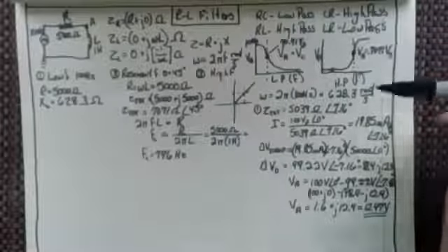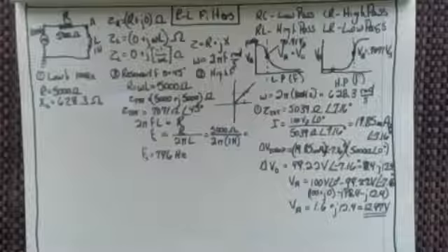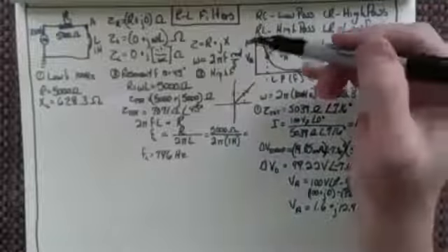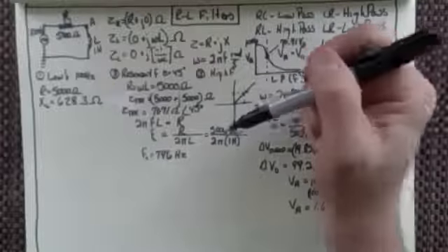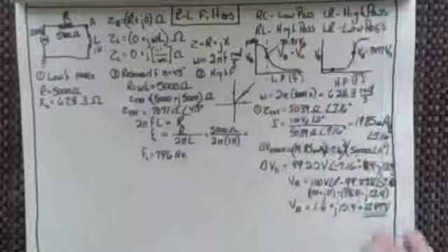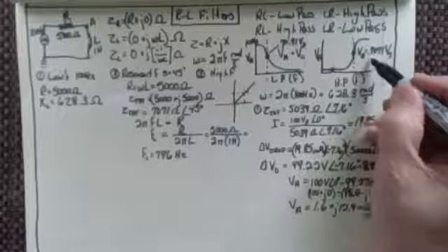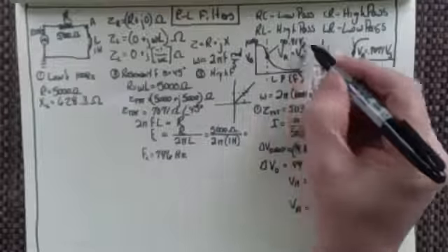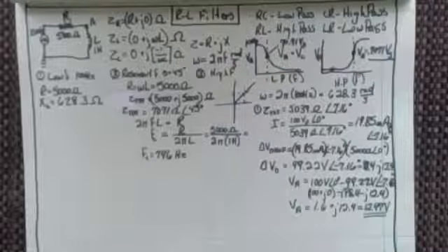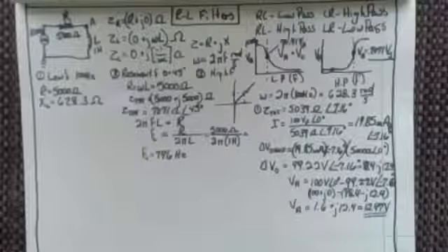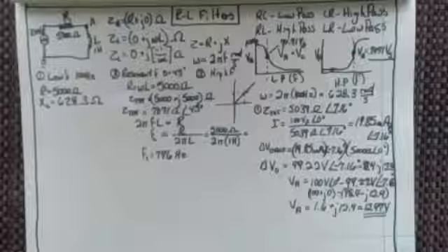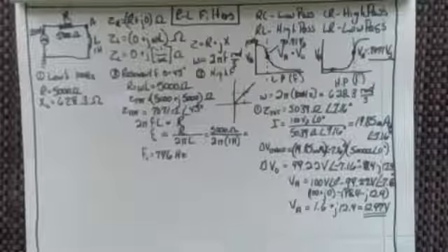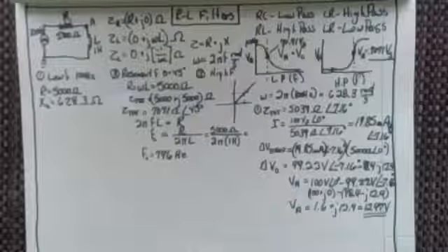Maybe we'll see how fast we can go through all of this, but I want to end up with a discussion about decibel attenuation and decibel amplification. And you'll see that 0.7071 and 70.71, like we've got there, is a very special place in both a low pass filter and a high pass filter and a band pass filter and a band stop filter, which are the 4 different filters.